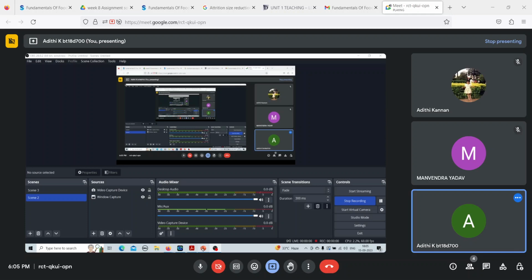And in the pin mill, this is how it looks. You will have tiny pins throughout attached on both the cylinders. And it is pretty similar to the hammer mill where you will have both impact and shearing. But then it will have much faster speed and you'll have pins instead of hammers here. So when you close this lid, your food particle will be stuck between these two rotating regions, which will have these intermeshing pins, and this will impact the particles as solids are directed through these pins. And after this, you will have your collection at the bottom.